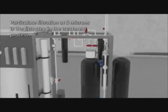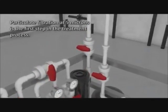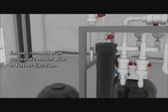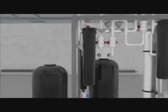Particulate filtration at 5 microns is the first step in the treatment process. This filter ensures that all particulate matter is removed prior to the next step of filtration, as well as less long-term maintenance of the RO membranes.